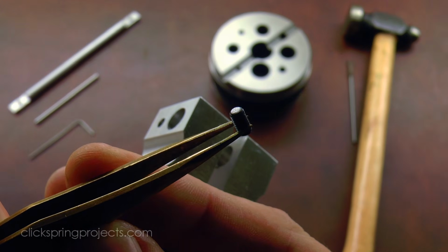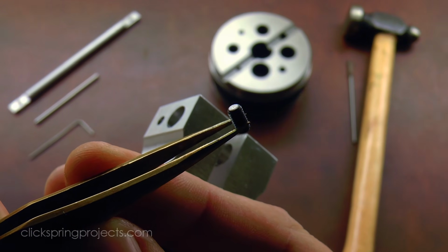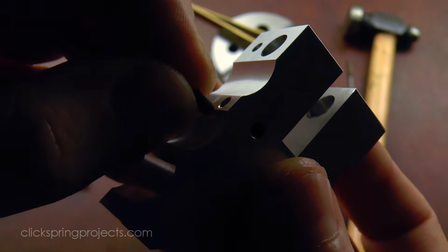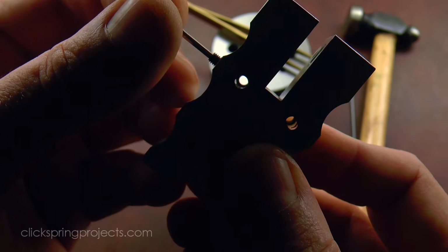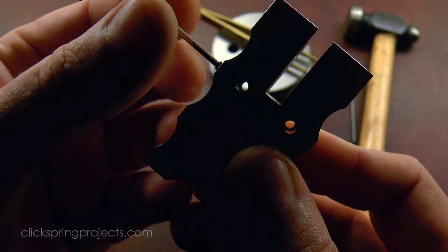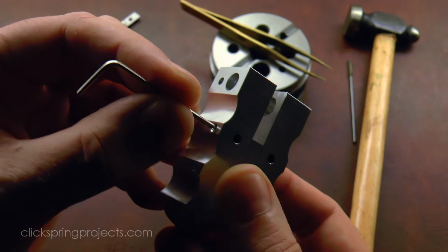this work. And just as a quick aside, I've rounded off the ends of the grub screws to minimise their capacity to bruise the button cutter shanks while they're still in their annealed state. Just a quick touch on an abrasive belt or stone and they're done.